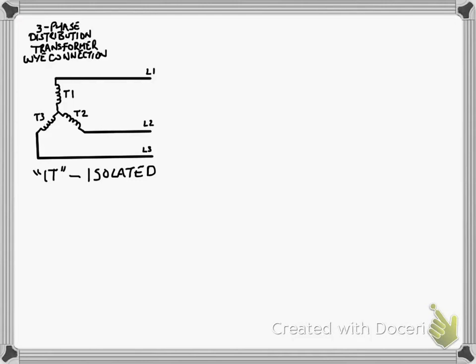That means that if we were to take a measurement between the chassis of the transformer or the alternator, we would find that we would have some indeterminate voltage between that center point and ground, and each of the phases might measure phase to phase 575 volts, but we'd have some indeterminate voltage between each of the phases and chassis. And there's a lot of technical explanation for why that voltage is somewhat indeterminate. I'm not going to talk about that right now.